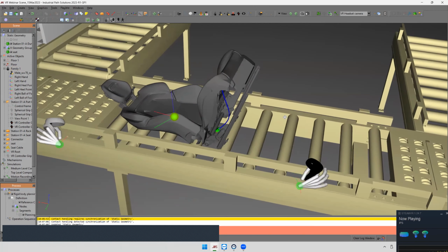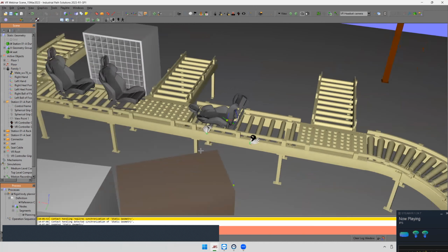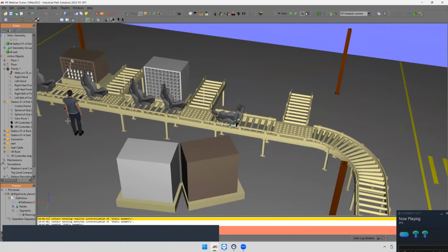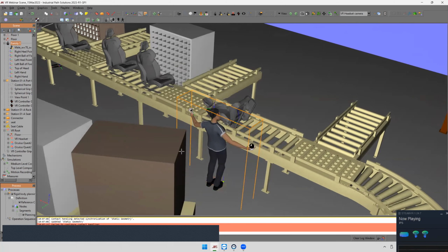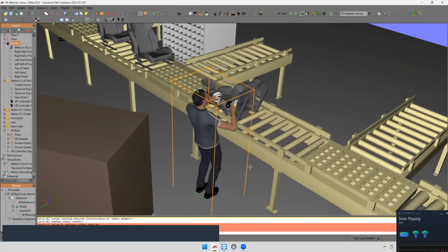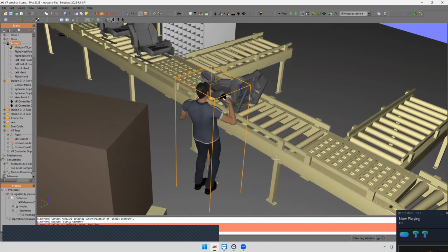And what I'd like you to do, John, is can you have that mannequin be attached to myself? One of the nice features that's been recently implemented into IPS and IMA is the ability to posture a mannequin by simply utilizing what's on you. It will utilize the 3 locations that it has, being your headset and the 2 controllers. And now we can see I have a mannequin which will follow my motions, and I can make representative postures of this.